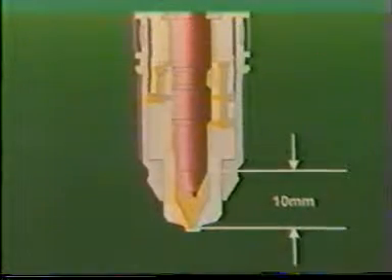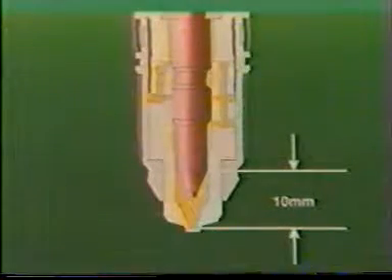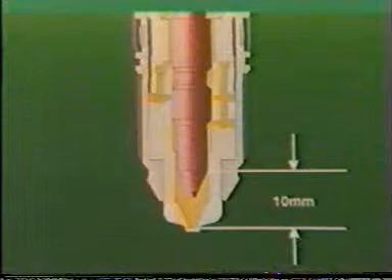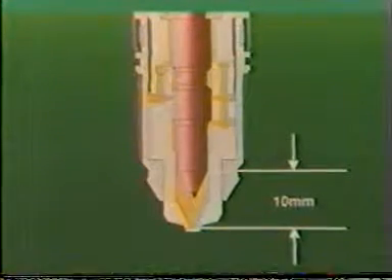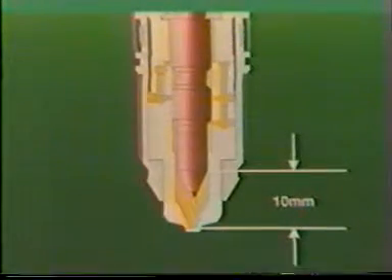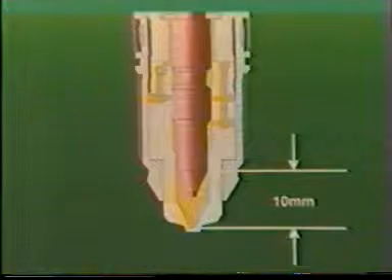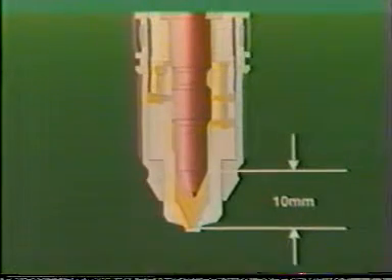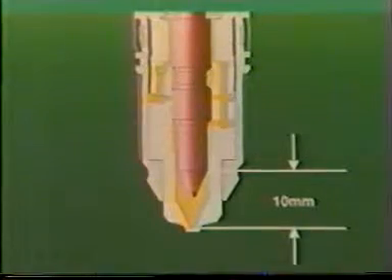The open nozzle design of the injector provides the ideal rate and shape of injection. A slow start of injection allows a slower burn at the beginning of combustion for reduced combustion noise. The sharp end of injection, eliminating secondary injection, provides reduced hydrocarbon emission. For every injection cycle, the stroke of the lower plunger is 10 millimeters.